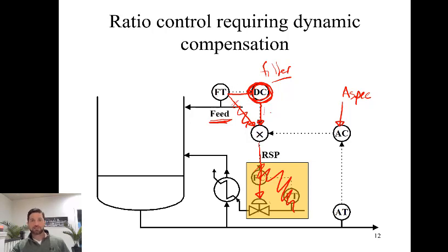is averaging a lot of different values that were before the change was made. This compensator is going to cause a gradual change in the feed flow to the system because it's measuring a lot of values that were before the change was made. Once all of the values are primarily based on the change, then the feed flow will be at the value in which the correct amount of heating is required to compensate for the change in the feed flow.